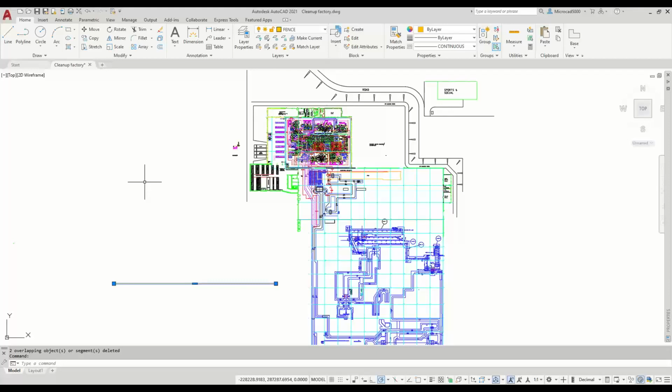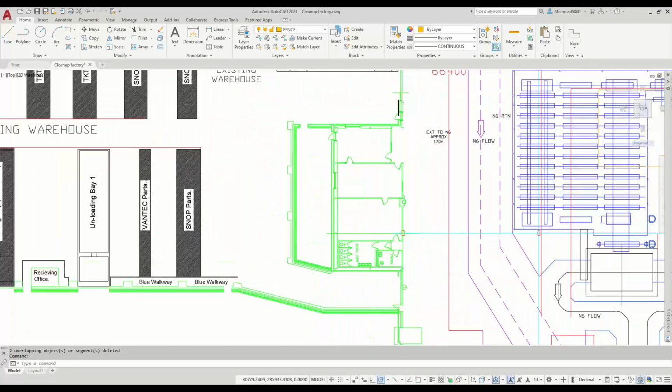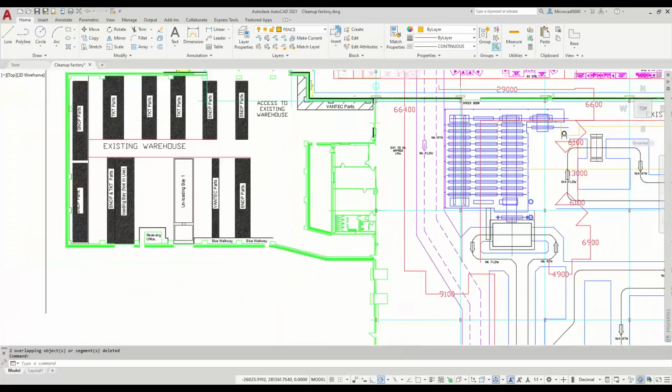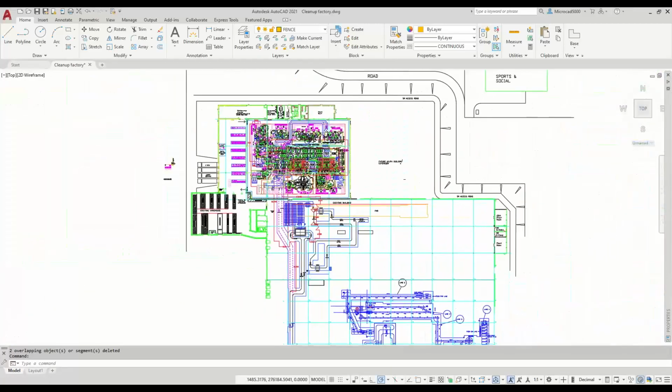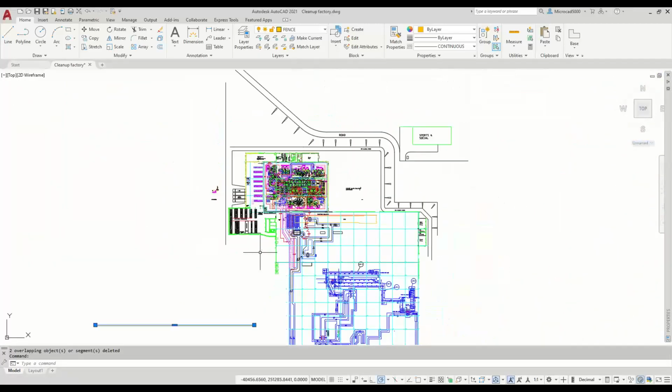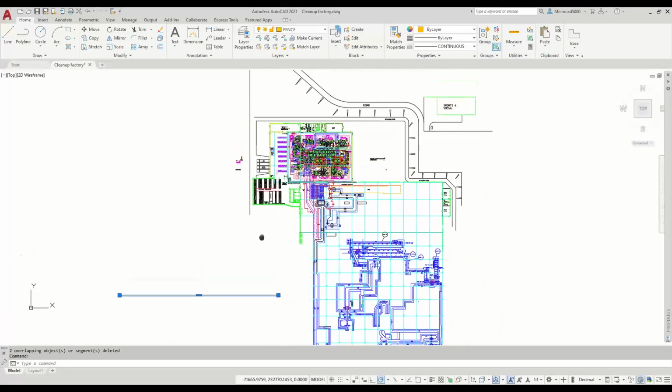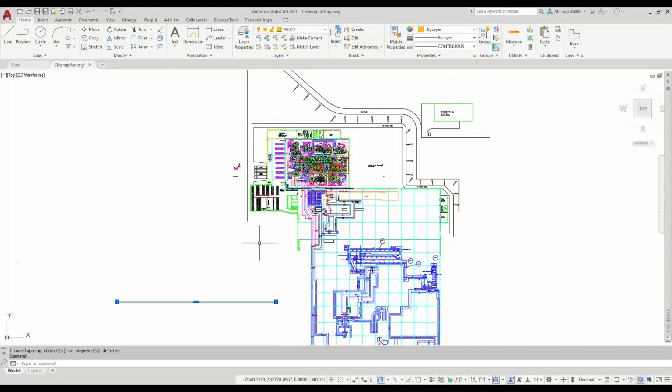Right, now this drawing file, I would expect if I zoom in, now I'll zoom into the area down here, it looks like it's got door swings on there. I would suspect it's a 2D drawing. Again, don't trust any drawing you get in because it will catch you out. Always check and double check.